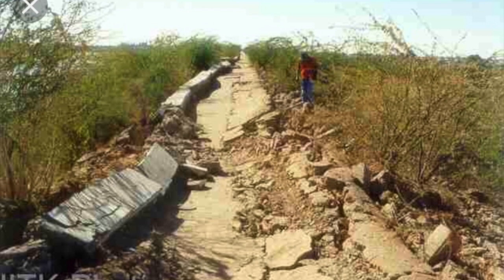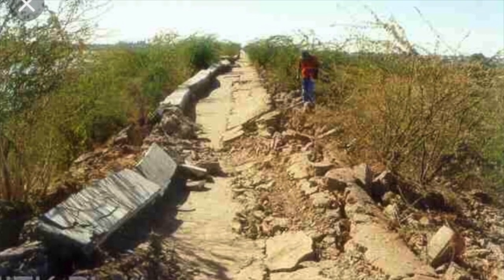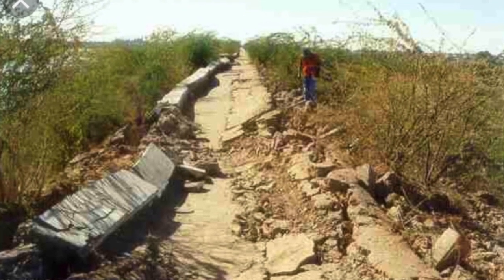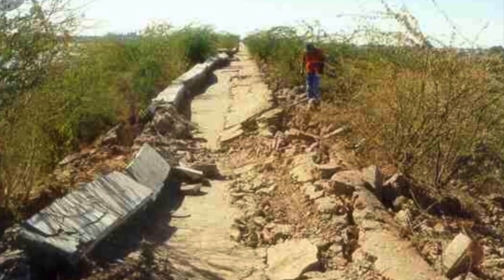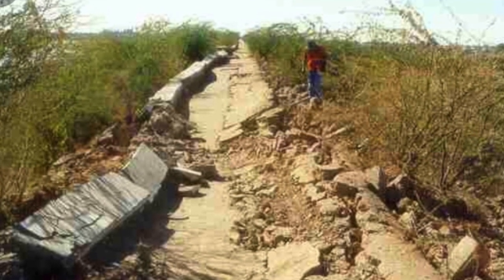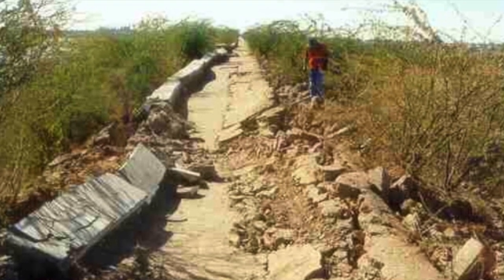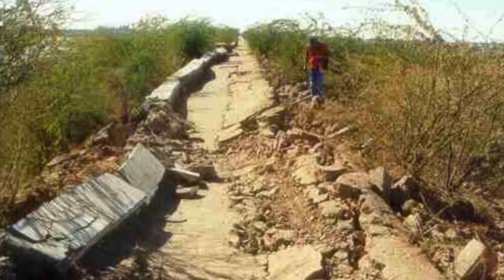In the construction of the dam then, we had to take into account the settlement of the dam itself. The dam will settle roughly 5% of the height. For example, our design height would be 3.74 metres, with the construction height being 3.93 metres.